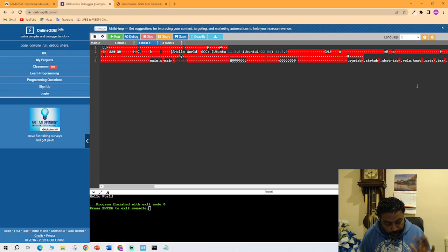Most commonly it will come in the .elf format. For example, Texas Instruments and other microcontrollers may want to use a different format, maybe hex format. To do that, you need to use objcopy in the ARM toolchain instead of objdump for analysis. You have to use objcopy, so you can convert from ELF format to hex or binary format.